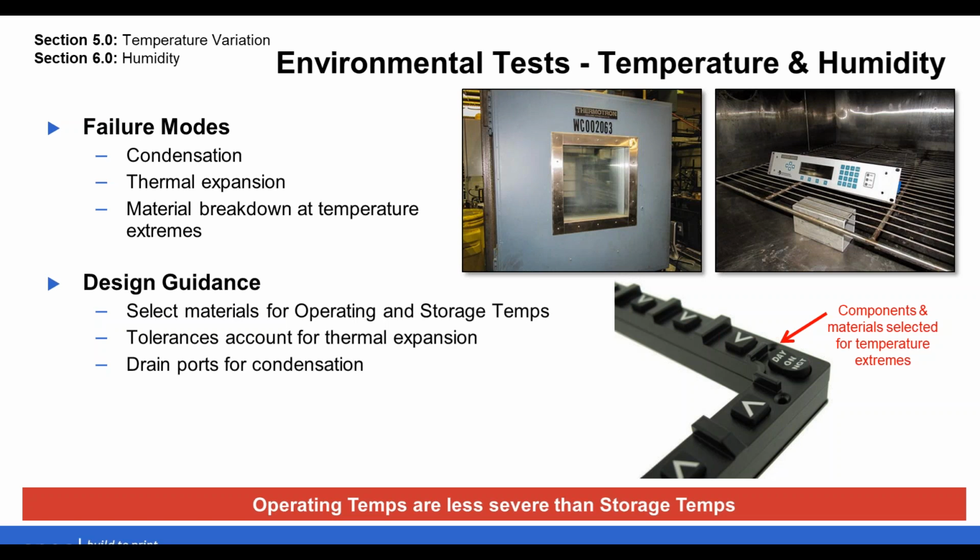Takeaway from this is that operating temperatures are less severe than storage temperatures. So your unit may only need to operate from -20 to +55 C, but it must be able to survive storage conditions from minus 40 C all the way to plus 80 or 85 C.